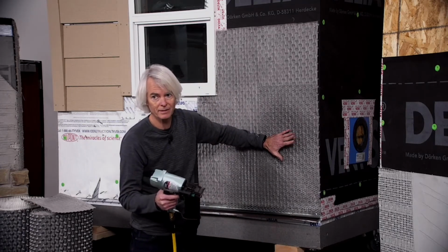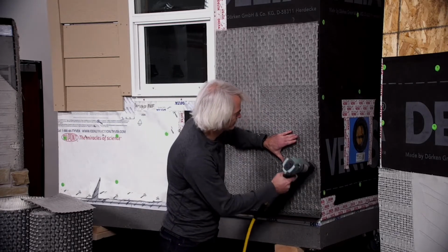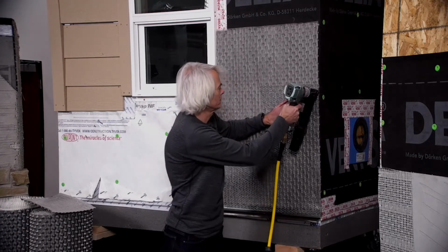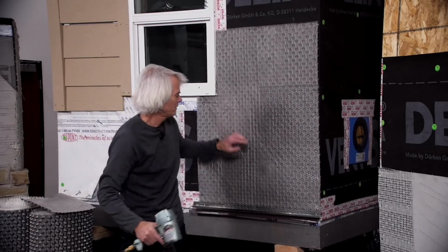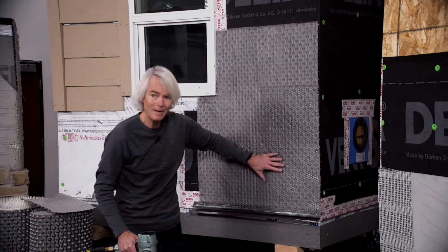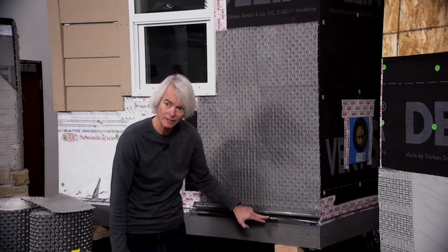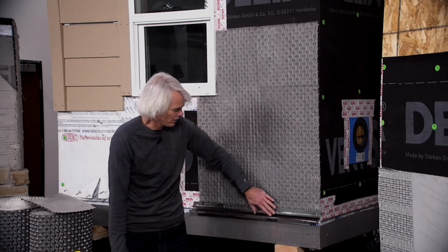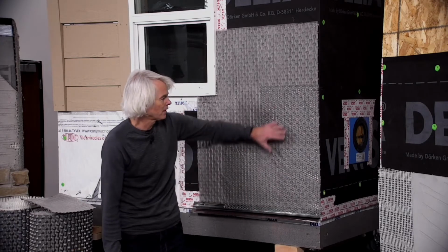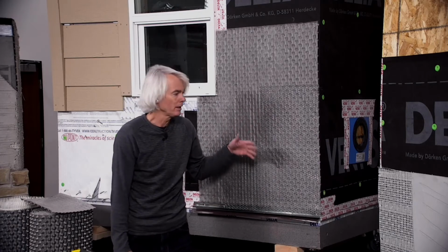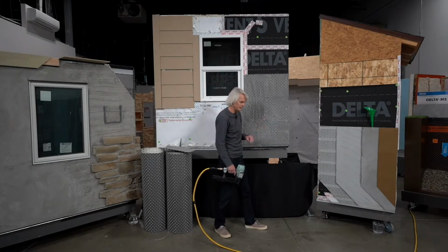We're going to use a 6-inch vertical spacing into the stud framing. That's a typical requirement. And we'll just put a few. So there we are. I'll leave a few ends loose. But basically at that point now we've got our metal at the bottom. So you can see we've maintained that gap where our diverter flashing works to kick that water out away from the wall. The weep screed weeps any water that's charged or held into that reservoir cladding, the stucco material. Our expanded metal lath, we're ready for scratch coat and the subsequent layers to finish this job up. So that's pretty darn straightforward and fast for an install.